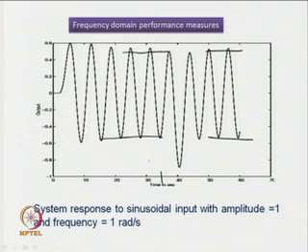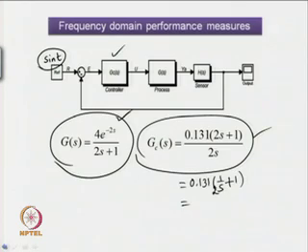Apart from this information that the system output is stable for sinusoidal input to the system, it is very difficult to make out any other quantitative performance measures from this output. It is difficult to visualize the good effects of a properly designed controller from this output. Therefore, we need to consider the loop gain of the closed loop system for frequency response analysis of the system.